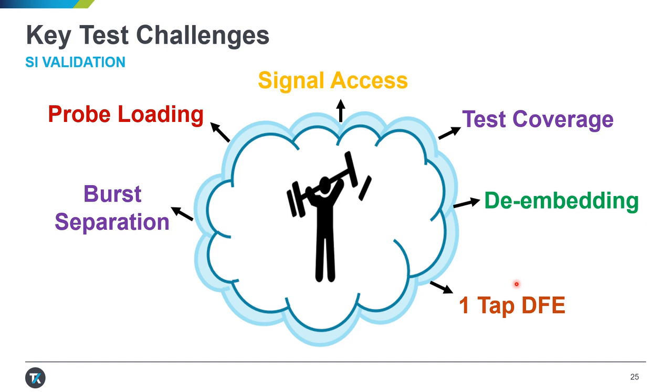And furthermore, DFE by nature is a closed loop system that requires a continuous pattern, while DDR by nature is a bursty environment. So this is going to be a problem to incorporate 1-tap DFE in our testing solutions.